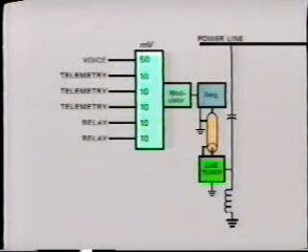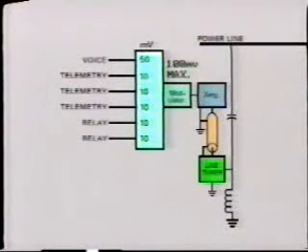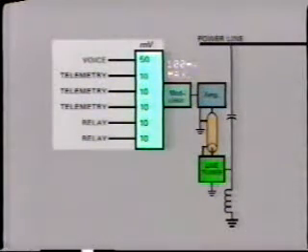We can increase the modulator output voltage only so much, say 100 millivolts, before we run into the problem of overmodulation, where the final amplifier starts distorting. So typically the voice signal would be assigned, say, 50 millivolts, with 10 millivolts each for the remaining 5 tones.